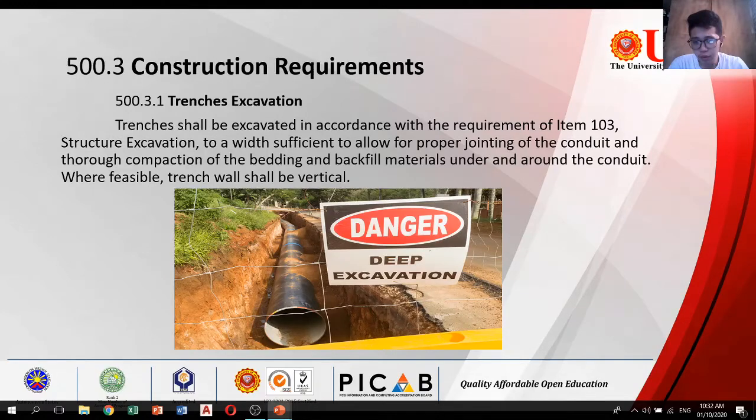So when specified in the plans, the excavation for conduits placed in embankment fill shall be made after the embankment has been completed to the specified or directed height above the design grade of the conduit.